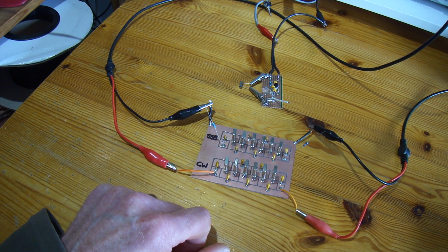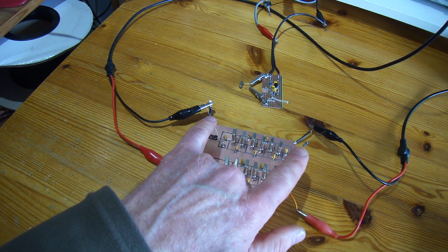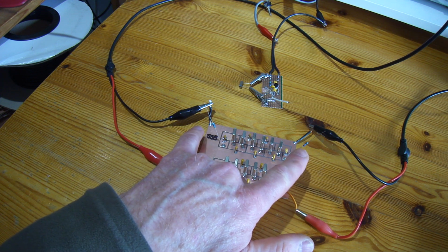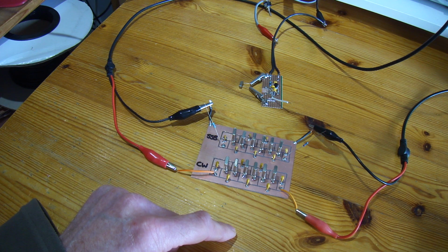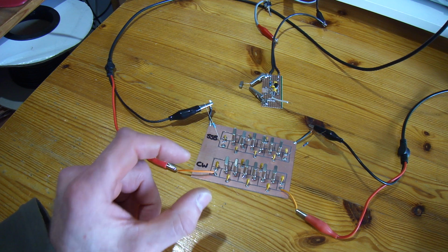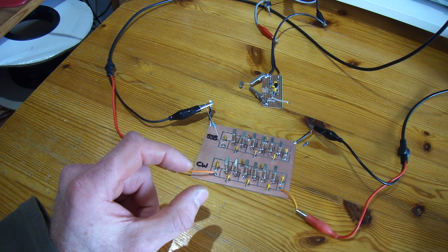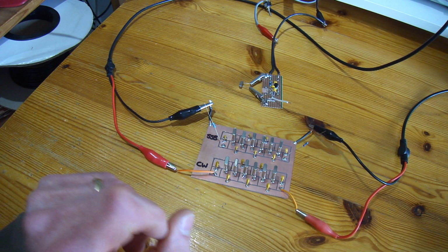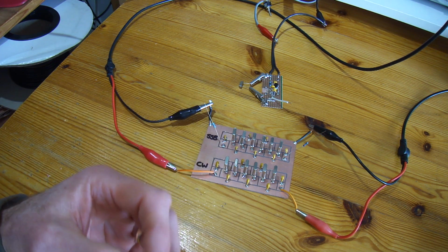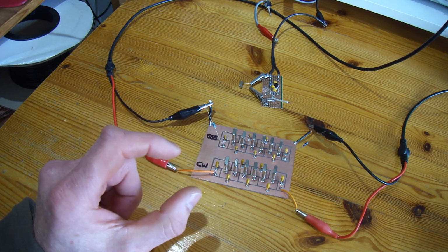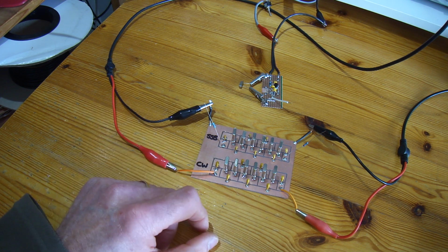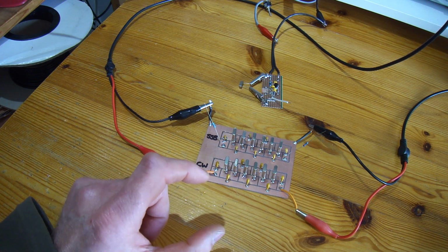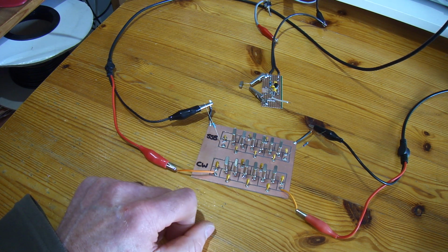No amount of adjusting the terminating impedances, or in this case resistance, if I ignore the reactance components, would fix it. So potentially, if I'd gone through a more rigorous approach and actually worked out for each crystal the inductance and the capacitance and the resistance, and then put them into a proper design program, chances are I may have come out with a better result. But for the approach I wanted to take, I just couldn't make the SSB one work.